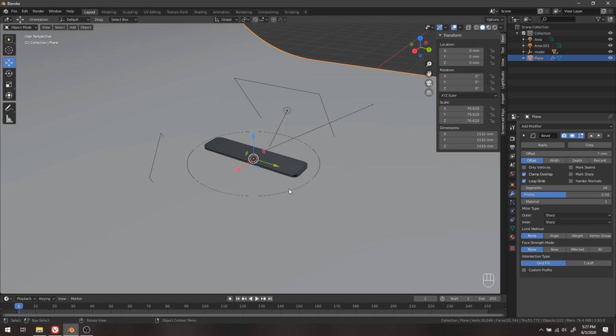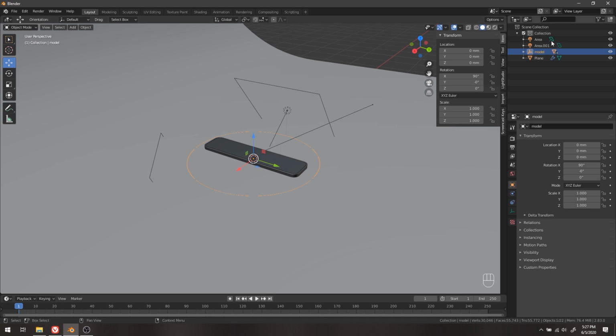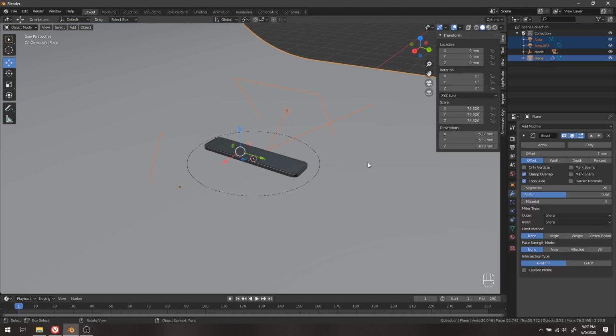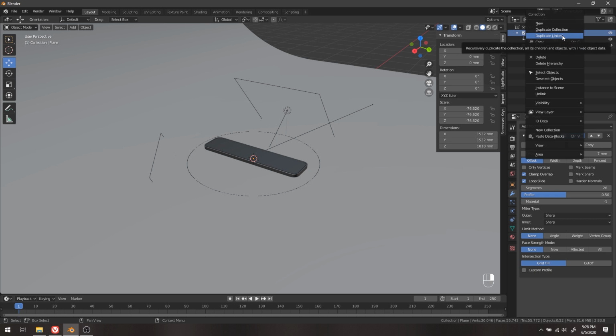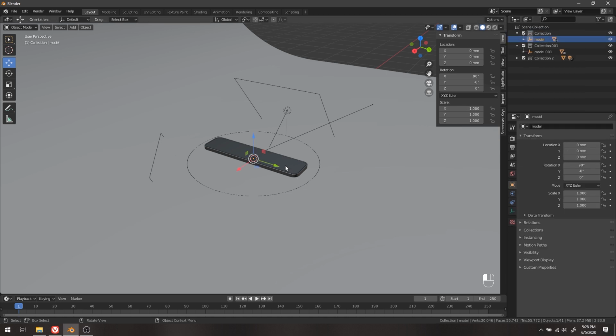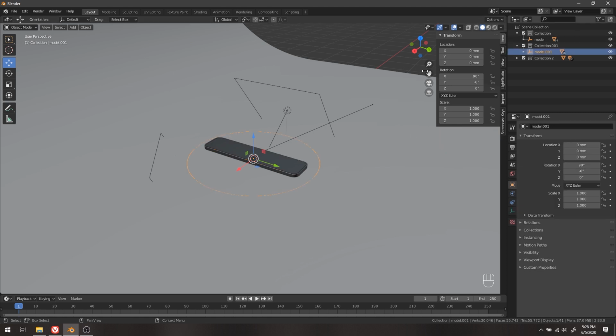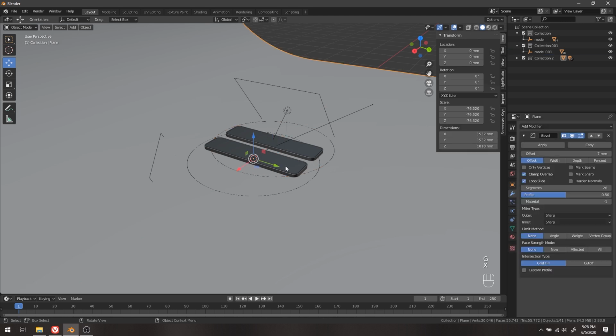The next thing we're going to do is give this guy a little buddy to float along with him. In order to do that, let's go ahead and move everything that is not the model out of this collection by selecting them, hitting M, and then making a new collection for them to sit in. And now up here on that first collection, all we have is that original model. What that lets us do is easily duplicate our object. And we're going to select Duplicate Linked with the right click. The difference between duplicate collection and duplicate linked is that whatever edits we make to this geometry will be translated into the second one. So you can go ahead and select one of the two, move it to the side, and then we're going to start organizing the scene.